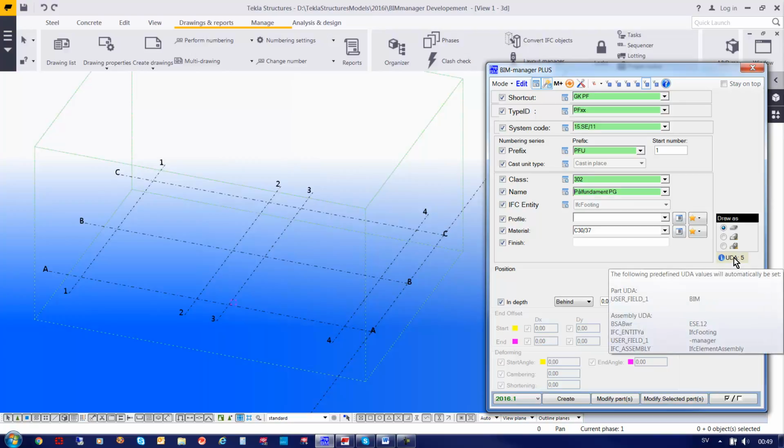Here's some extra UDA BIM data. All the Tekla data and all the BIM data, or 100% QA, selected directly from the database. In 4 keystrokes and Enter, you have selected all Tekla data and BIM data from your database needed to create your pile foundation. You can also see that the available part types have decreased to those you have predefined in your database for this cast-in-place foundation.